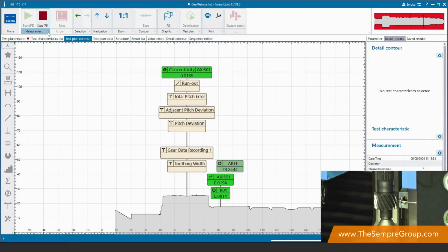So there's a key thing to note when we're talking about gears, especially in the sense of the probe that we've got on the machine. The probe that you can see here has a larger Z negative length. The idea behind that is that we can use that probe to come in on the internal of parts. So you can imagine we had a spline on the inside of a component. We've got some external geometries that we'd like to use the system for, and then we want to bring that probe in to measure the internal feature. So that's what the ability of having the longer Z negative probes will help us to achieve.